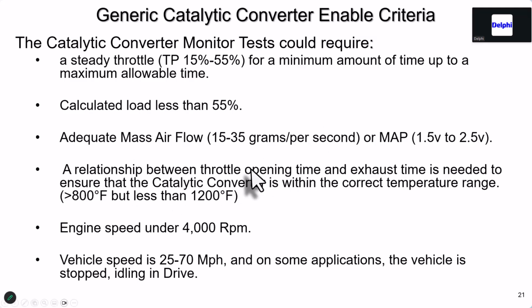Once again, they infer temperature of the exhaust. Look at your global scan tool. Start developing a window. My experience has been, and there's always a fudge factor in here, I usually use 800 as a window, as high as 1200. But there's a case study I'm finishing up today, and I've got their CAT running at 1500 when it runs. Vehicle runs great. It's sitting at 1500. That GM seems to work fine. But this is a good window if we're in that window. And if you're at 1500 degrees and there's no misfire, then just accept that that's the way the vehicle runs. But if you can feel anything, then that temperature is being inferred and there could be a little misfire going on too, but not enough to stop the cat from running.